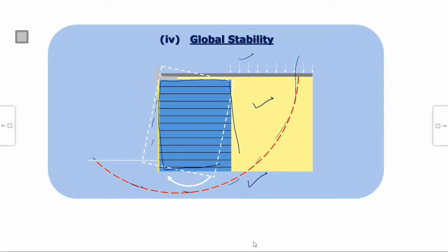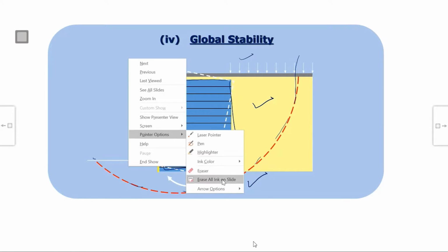I will just name them. I will not go into those details. There are graphical methods by which roughly you can calculate the factor of safety. So maybe for initial design, you can use those graphical methods. It is given in RDSO G18 also. But most of the designers always in the end, you must check it using a suitable slope stability software.